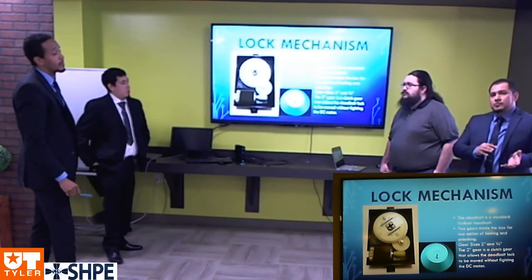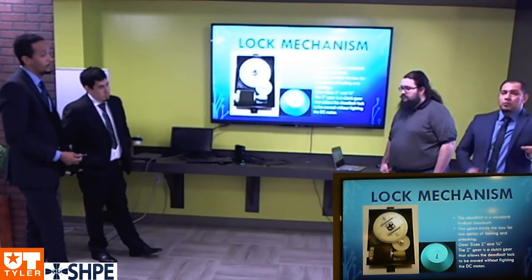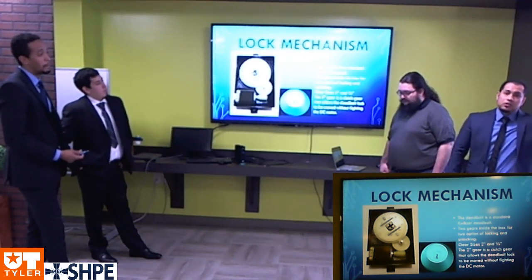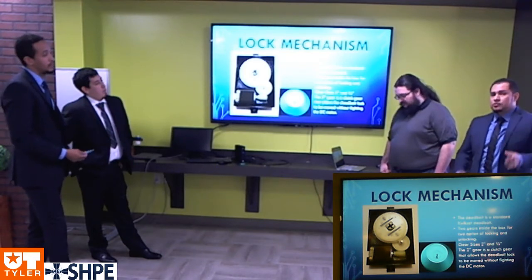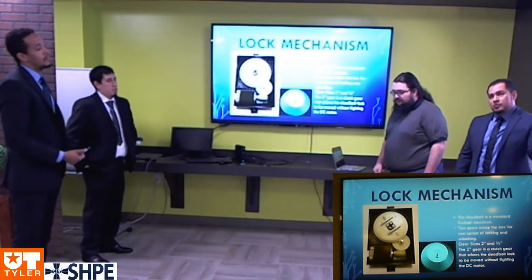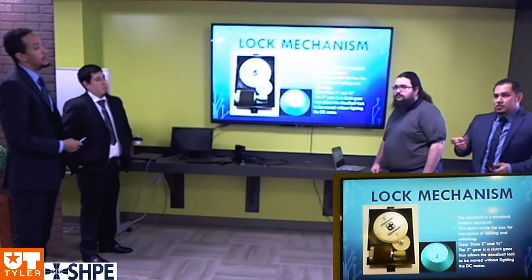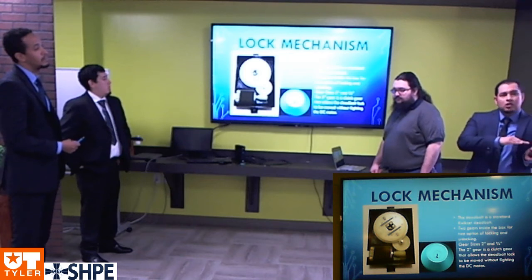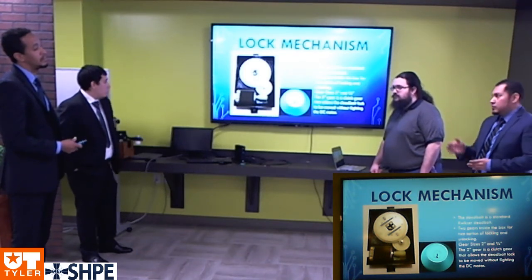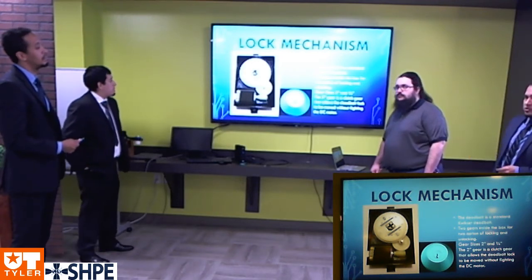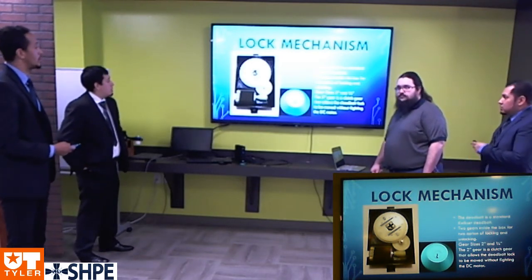So what happens if you only have it going one way, right? It's going to try to go another 90 degrees, which will be 180 degree rotation. But we don't want it to go that way. We want it to go negative 90 degrees. So that's where that chip comes into place. That way the latch can come the opposite way, like if it was actually a human hand moving it. It will rotate one way to lock and the opposite way to unlock. And it's necessary to have that particular chip in order to make the gear go like that.